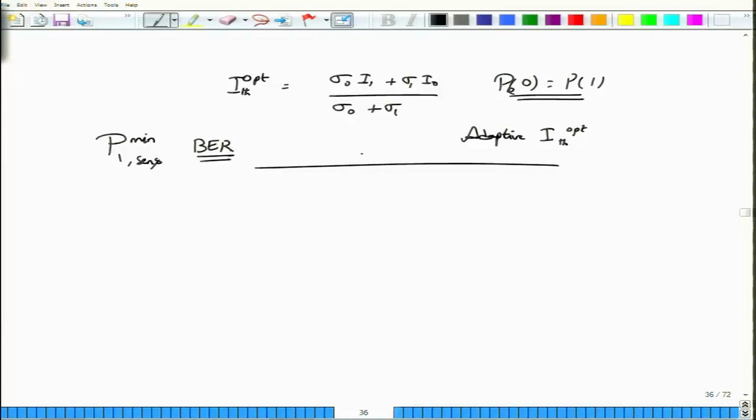We will not touch that particular topic, but to tell you that coherent receivers, which we are going to discuss in the next modules, offer, for the same operating conditions, about 3 dB more sensitivity, that is you need 3 dB less power to maintain the same bit error rate compared to the direct detection receiver. So, this also you should keep in mind. Anyway, all that we discussed previously was without the preamplifier.